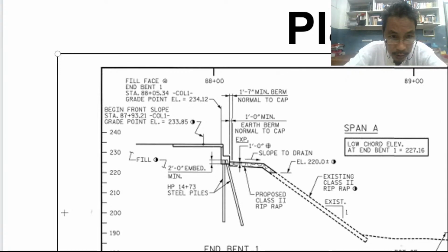So fill, therefore, as you can see, is expected to be what? The soil. And when you fill it back, what will you do? You will stamp it, compact it. Compaction of the soil must happen. That is a process wherein we address unstable soil quality.